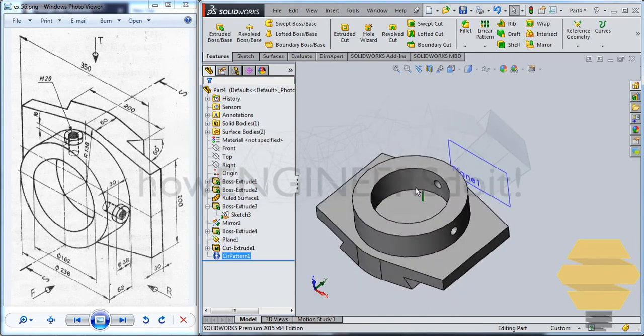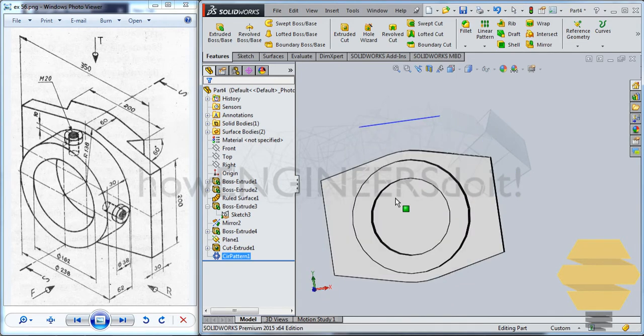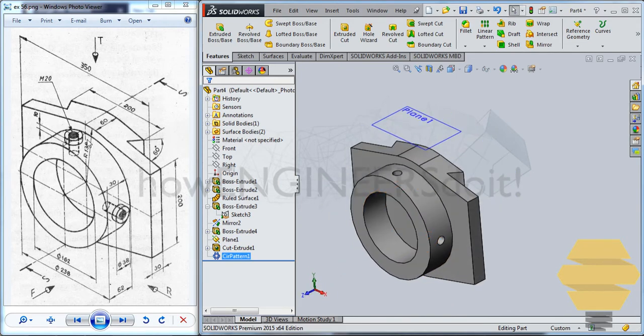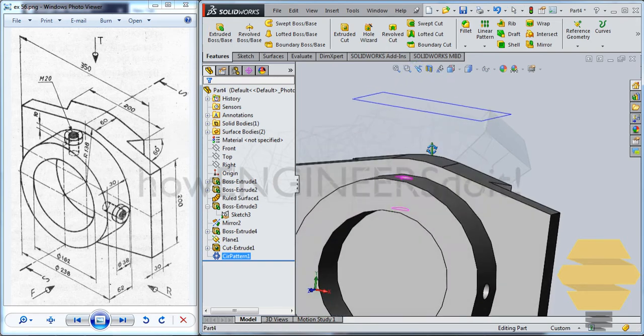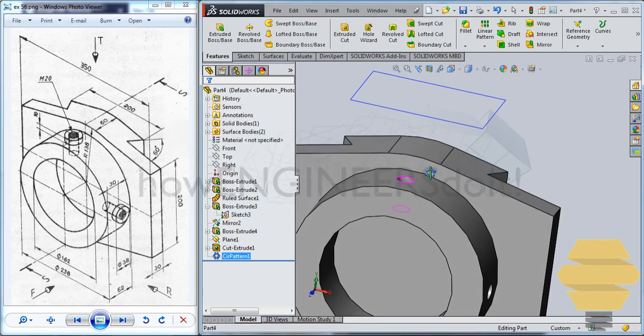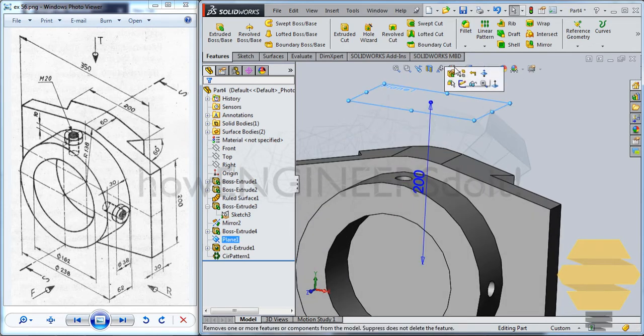And now what you can do is to create a model that resembles the model of a screw. So in this case I'll just design only 2 cylinders which are of different diameter. So to do that, what you can do is just go for the plane here.